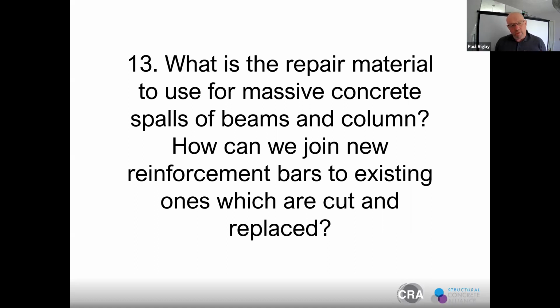If you've got loss of reinforcement through corrosion, then another consideration could always be composite technology, where you're adding carbon fibre to the outside of the structure to strengthen it. So that's something also you could consider. And there's plates and wraps, different products you can use. So yeah, composites is something you could always look at.